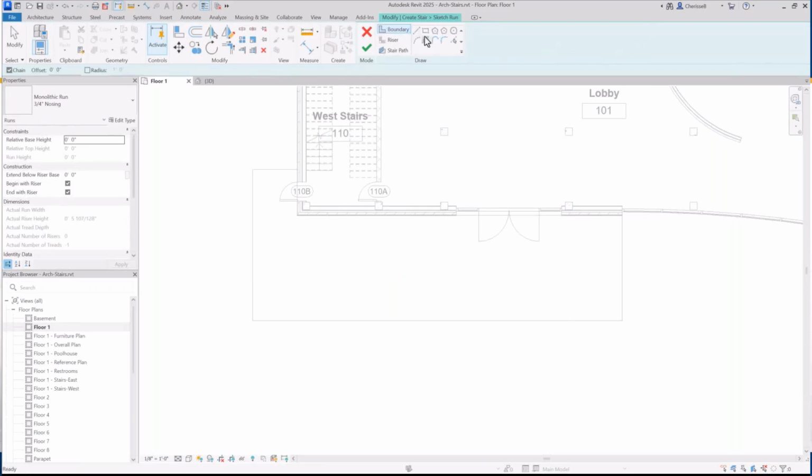And because I have a template of sorts of where I want these stairs, I'm going to utilize the pick line for the boundaries. So the boundaries are on the opposite sides of the run. And this step is going to be L shaped, so it's going to have steps on the front of the building and the side of the building.